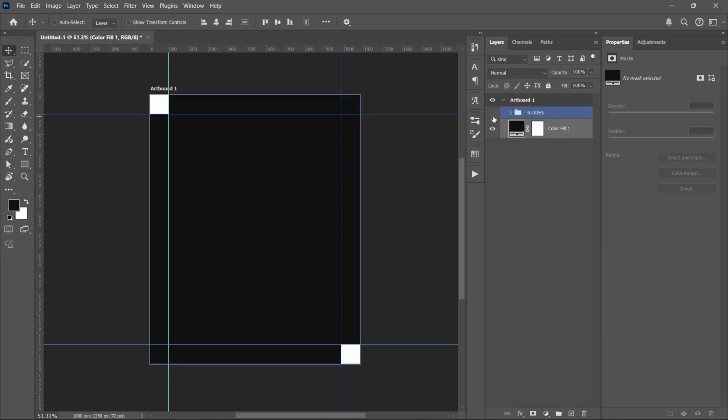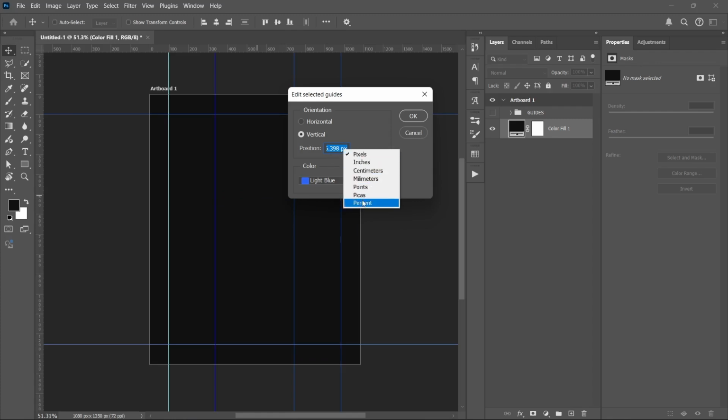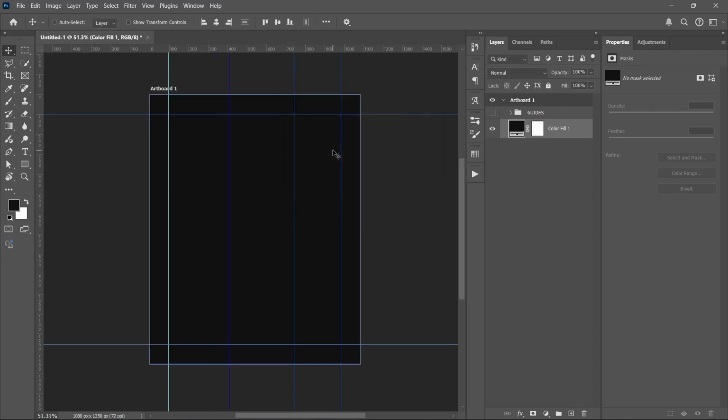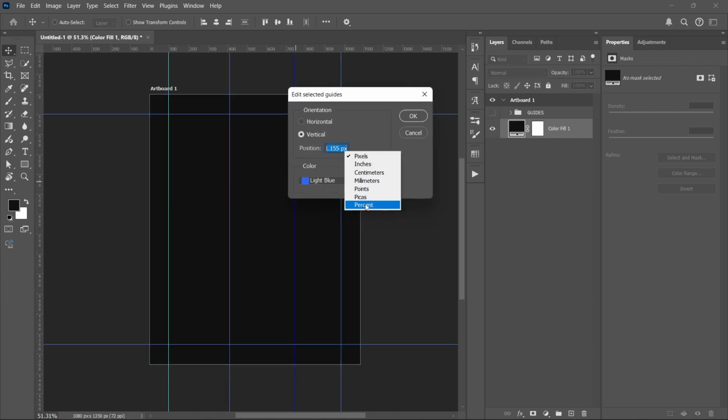So now I'm going to hide the guides, and you can see that we now have these coordinates, but it does not end there. I'm actually going to do some more coordinates. So I'm going to bring in 2 more for the vertical section. Bring in 2. This one I'll right click on it and change it to percent. I'm just going to use 38% here. And for this one, I'll right click on it and I'm going to use 77% for this one.